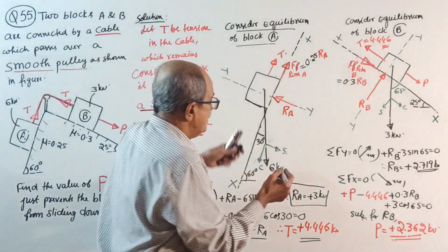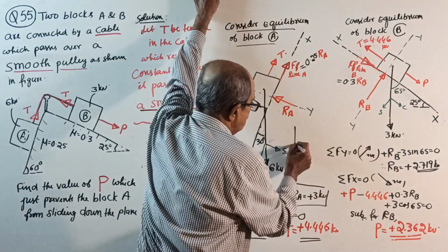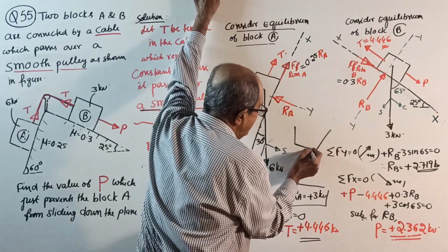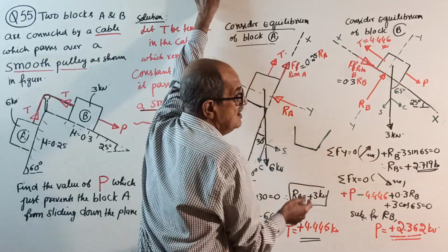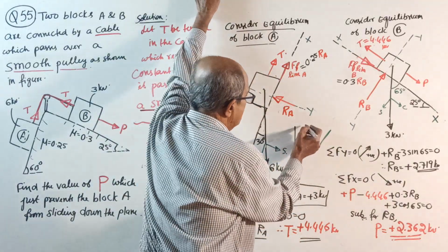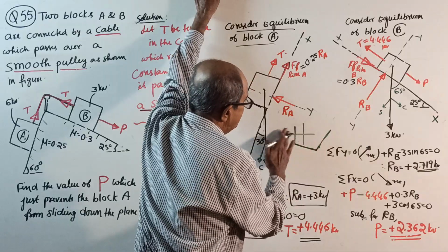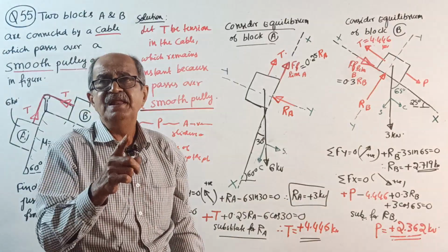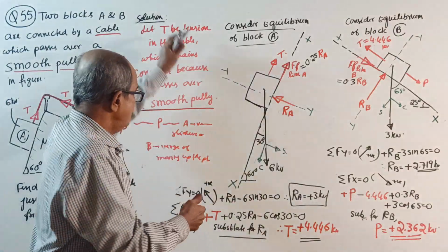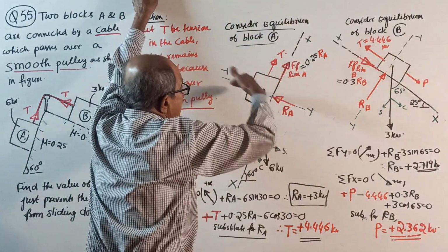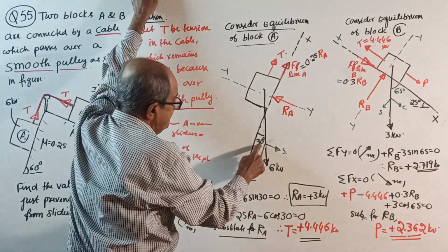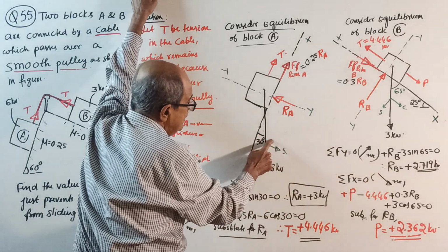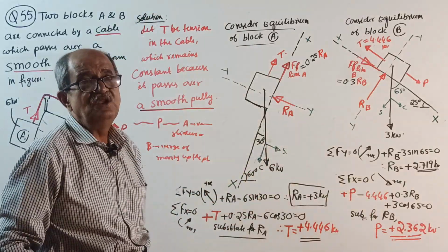See, when you go to wedge friction later, some questions will come, like this way and then this way. One inclined plane here. Then you cannot take, as usual, X along the plane; you take X horizontal, Y vertical. At that time I will tell you. So whenever only one inclined plane is there at a time, you take X along the plane, Y perpendicular. So if it is 60, this is 30, see, cos, sine. If I explain further, someone should walk out and tell me I am wasting time.